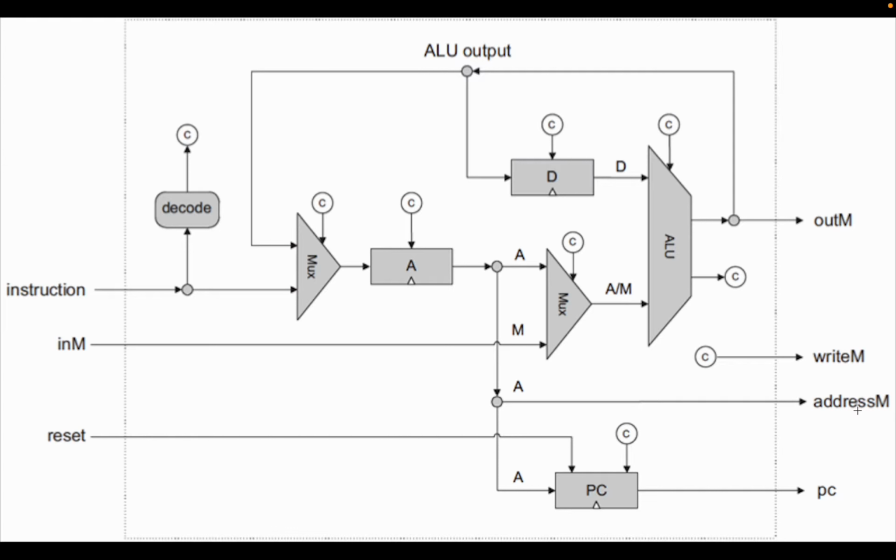On the other hand, the A register stores the value that is fed to it, and it takes in the output of the mux, and the outA generates the value that is currently stored in the register. Next is the Mux16, which takes the output of the A register and the value currently stored in the data memory, M. Either A or M will be fed into the ALU depending on the top bit of the instruction.